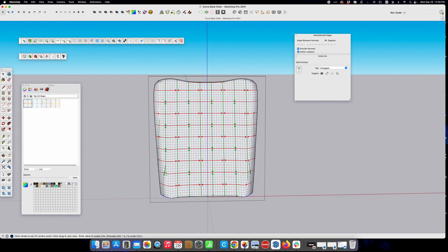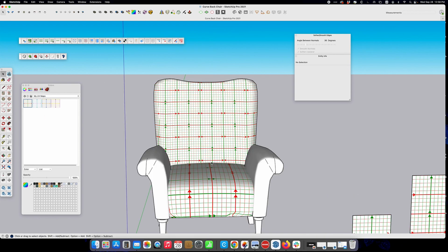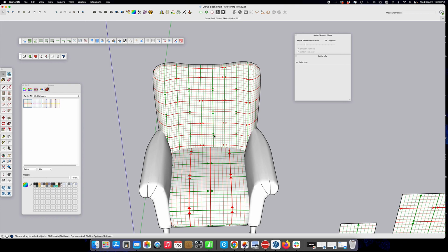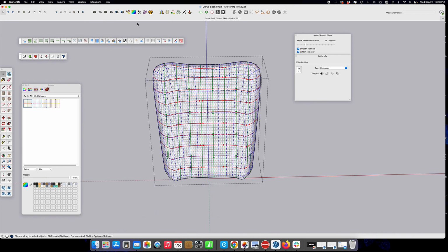It's a little fussy. It's not 100%, it's not going to be exact if you want it to match up to something else. For example, if I want it to match this, I don't know what to multiply it by in order to get it to match this. If I go back in here and I say SketchUV and box map again, it resets it, and then I can try ×2.